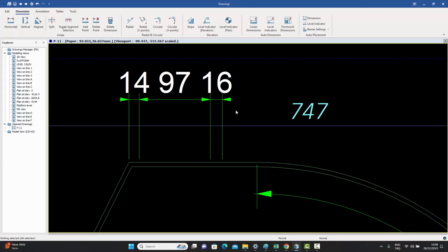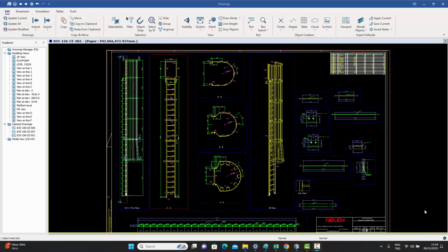When I placed the dimension previously, even in the first and last sections there would be two arrows, just like in the middle section, where you see an arrow like that and an arrow like that. It would be the same over here. And those two arrows would sometimes, because this region is so small, basically merge into one. So in this version, we have changed it for the first and the last dimensions. If they have enough space, then it'll behave the same way. But if they don't, then it'll just convert the arrow into something like this from the outside, and that'll be a cleaner way of showing the dimension.